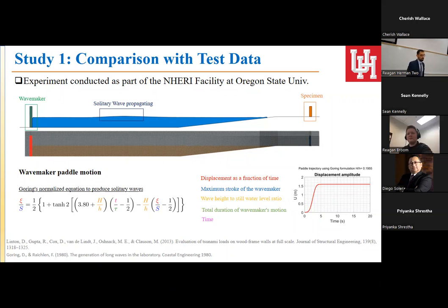Okay, so what kind of waves do we produce to study this phenomenon? Both in the validation study and in our study, we used solitary waves. The reasoning is that solitary waves are a specific form of wave whose nonlinearity basically counters the trough of the wave and just leaves a crest. This way, we feel it's much easier and more intuitive to understand how the wave interacts with the structure, because you don't have another wave coming in.